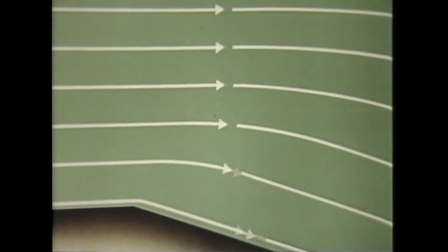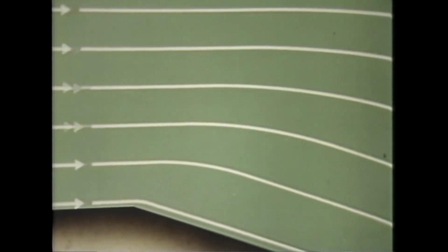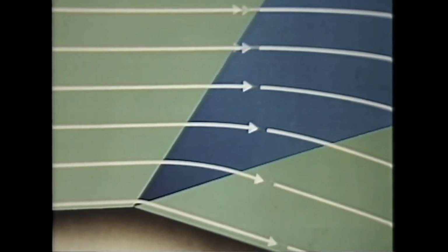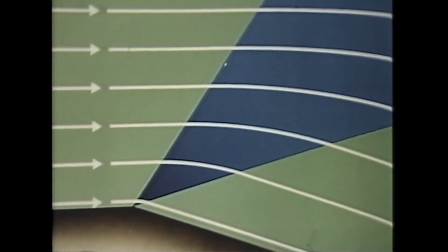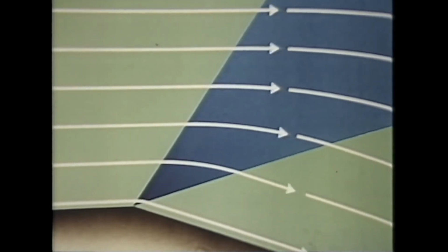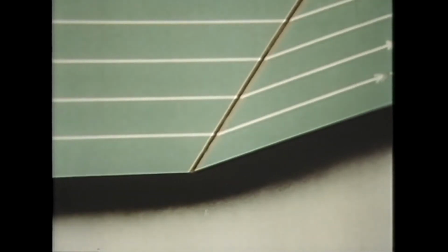But supersonic flow, surprisingly enough, can turn the same corner easily, as shown in this diagram. As it does so, the air expands through the region shown here in blue, and pressure is reduced. A sloping shock wave, coming from the opposite kind of corner, swings supersonic airflow smoothly the other way.